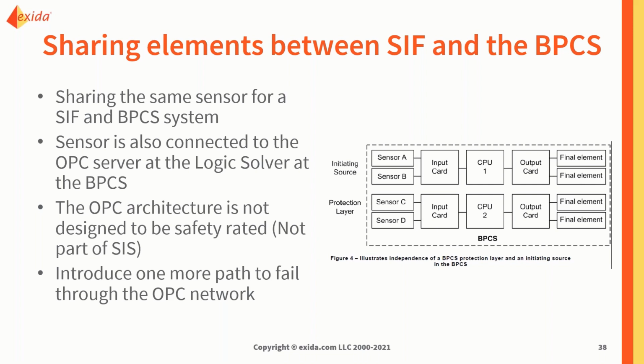And that is actually going to cause a lot of problems, not just on the OPC side, but within the SIS system, within the BPCS system, and even for cybersecurity. I keep hearing people ask me during the heads-up session, oh, can I share the same sensor or the same valve, which is even worse for a SIF and a BPCS system.